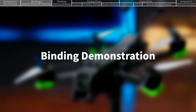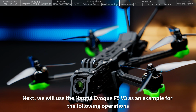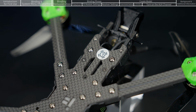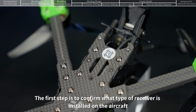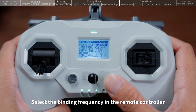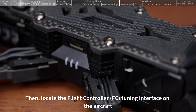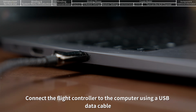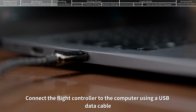Binding demonstration. Next, we will use the Nazgul Evoke F5V3 as an example for the following operations. The first step is to confirm what type of receiver is installed on the aircraft. After confirmation, select the binding frequency in the remote controller. Then, locate the flight controller, FC, tuning interface on the aircraft. Connect the flight controller to the computer using a USB data cable.